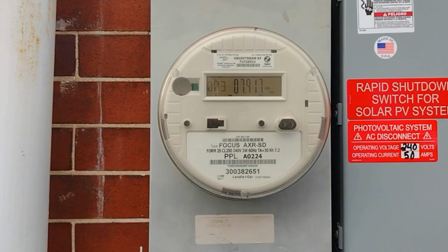Window number 3. This is kind of specific to PP&L, because different power companies use this window for different readouts for whatever reason. But PP&L specifically uses this for your peak usage over 24 hours. Now this one does reset daily. And this one shows the highest point of power consumption during the day, at any given point of the day. Generally, a peak meter is used to make sure that you're not pulling too much electricity through a system so that you're not driving it too hard, overloading it. You don't want to overload an electrical system because it's going to possibly cause a fire.